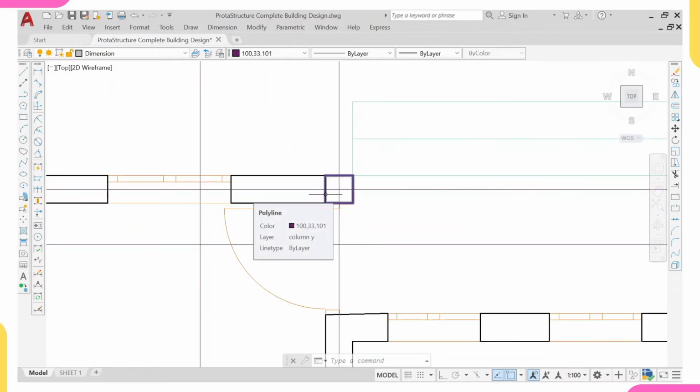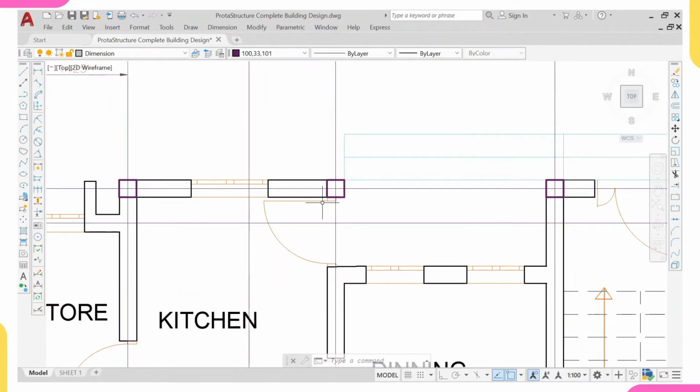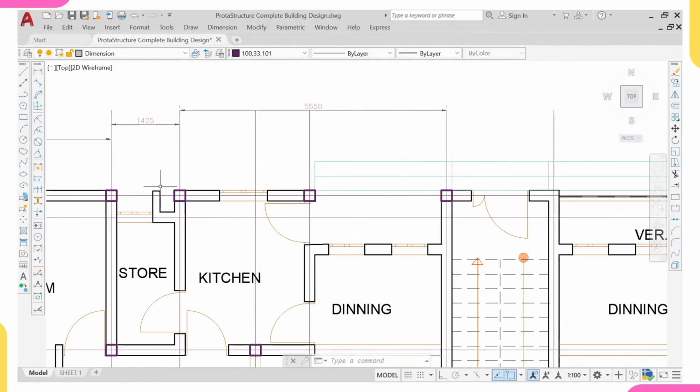Don't forget again, if you remove this column in your design, you might be having 3y16. Leave it, it is okay. If the client should complain that he's having 3y16 but the other project is 2y16, explain to him. He doesn't know. Most of those projects, maybe they're having a column here, a column here, and also a column here. If you have columns here, here and here, your work must be 2y16, it is a must. But if you remove this, that means the probability of you having 3y16 has increased. Yeah, here might be 3y16, but even though it is 3y16, you are still saving cost.